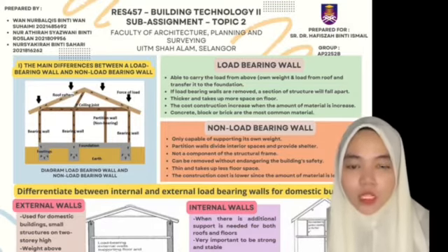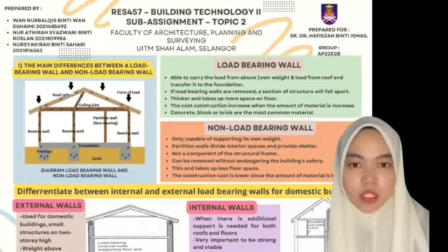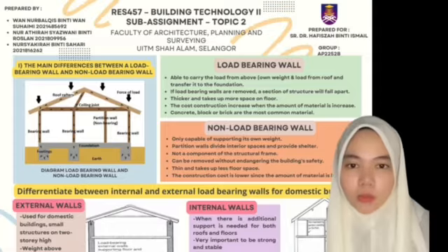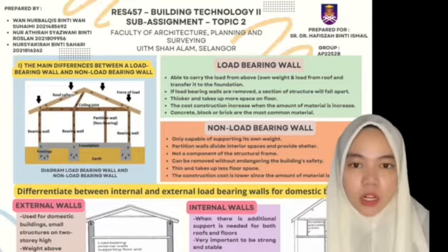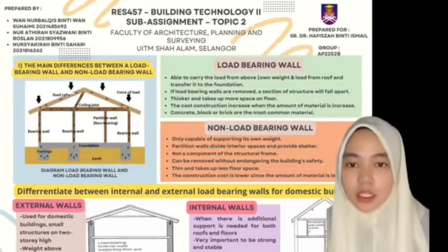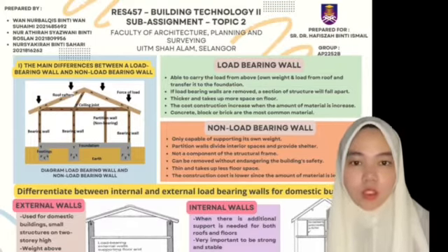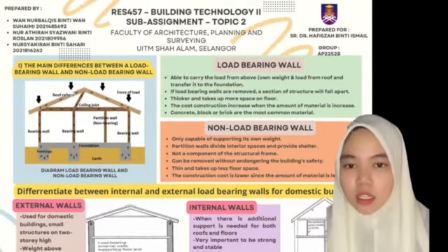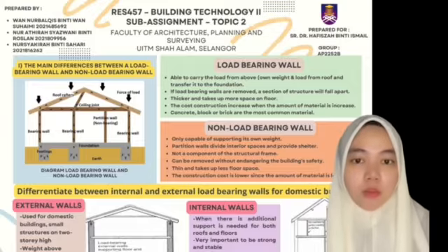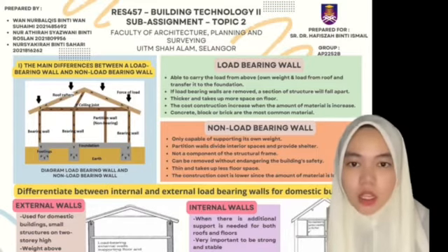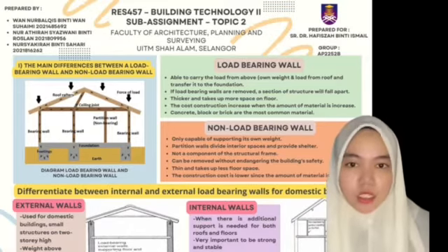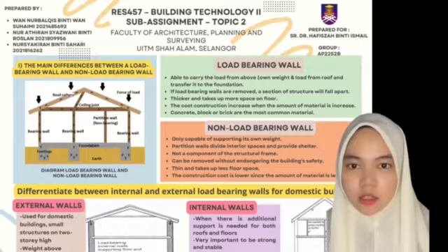The load-bearing wall is very important in many structures of buildings, as if we remove it, the other structures will fall. While the non-load-bearing wall is easily removed, as it only acts as a partition wall to divide the areas in the buildings. The load-bearing walls usually take up more space on the floor, as they are thick, while the non-load-bearing walls only take up less space as they are just thin.